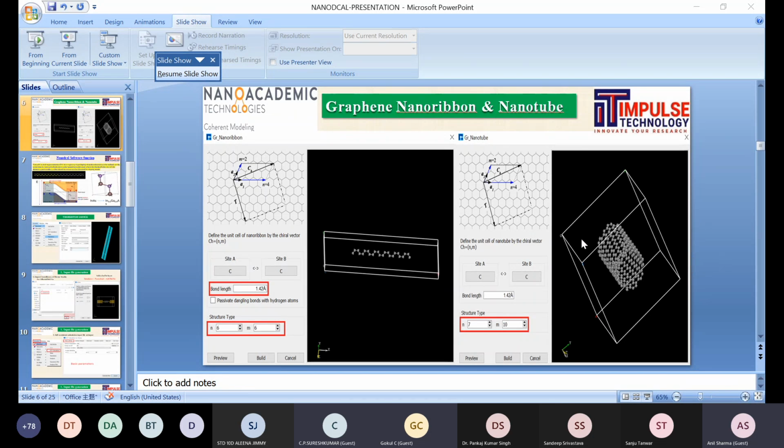So you can create electrodes, anode and cathode, define them, and then substitute the molecular structure in between to form the device. So there is a left electrode, center region, and right electrode. These are two-terminal devices where anode and cathode can be created with center regions. And then you can add buffer layers in between, so it can be easily created. There is a variety of file formats that the software also supports.